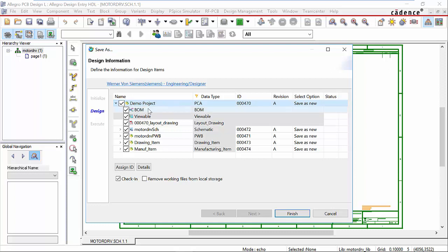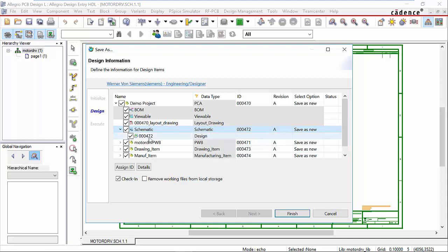We will generate a bill of material for every project from a parts list from the design and a schematic visualization file. In the Allegro integration to Teamcenter, we create a separate part number for the schematic data. So all of the schematic data will be in its own part number and separate data object. We can change the name for the schematic part number. If we look under it, we see the data object, the data container for all the schematic data.